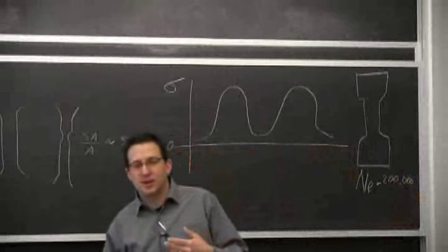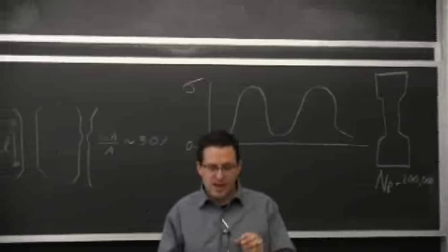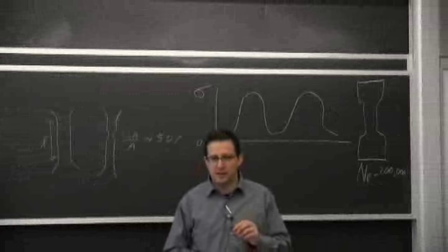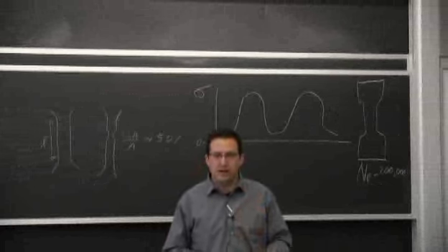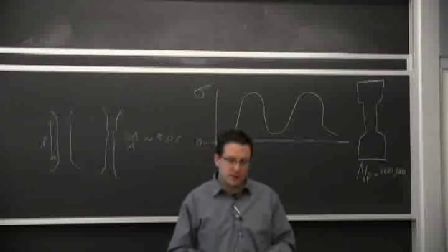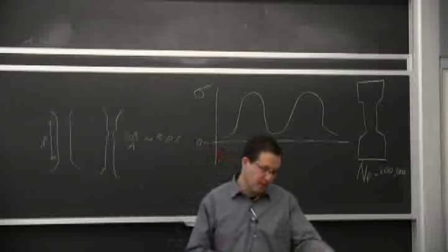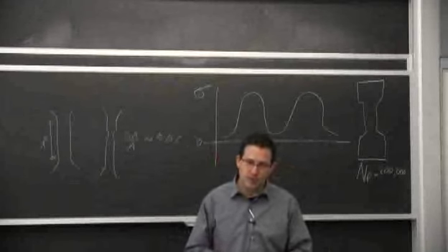You don't know out of that 200,000 cycles how many were for making a 0.2 millimeter crack, which is about the size you need to actually see it with your eye. So we don't know the time it took to get to that point, as opposed to making it to what we have in the image, which is more than a 1 millimeter crack.